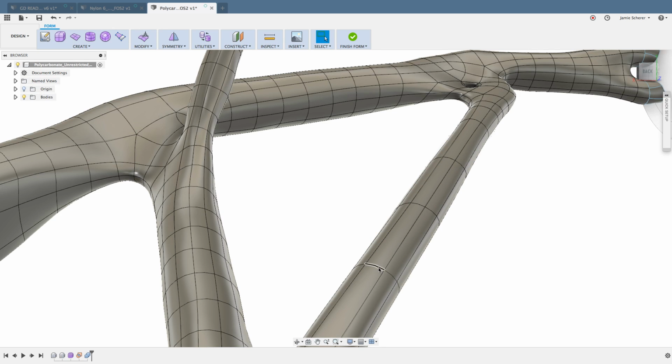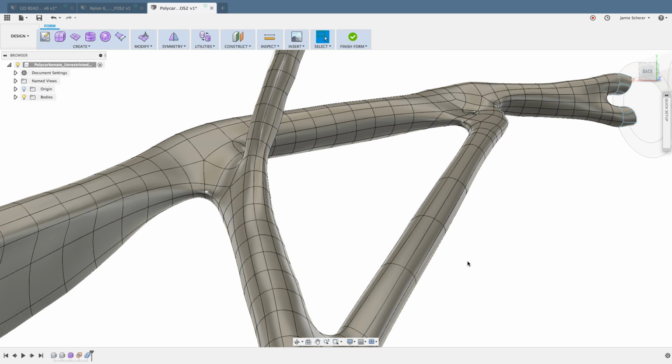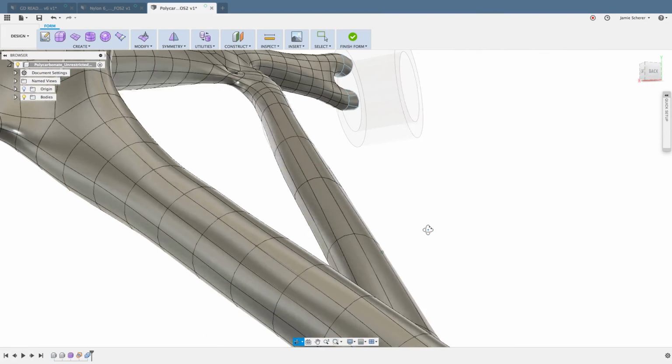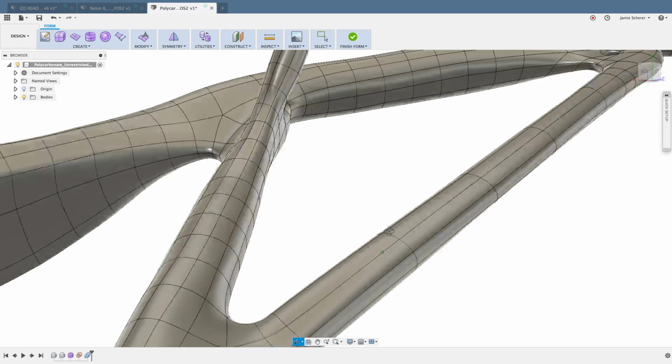Now, the distance or the change in shape between these two edges is no different, right? You can see that in this case they're not perfect circles, which is okay because we're creating something that we know we're probably going to print on an additive printer. But those two profiles haven't changed. The amount of spans or edges between them is only one, where before we might have had 3 or 4, which was causing it to have lots of imperfections across that span. So just by deleting some edges, whoops, and we will try to get that so it's not in our way, you'll see that this is already quite a bit smoother than it was before.